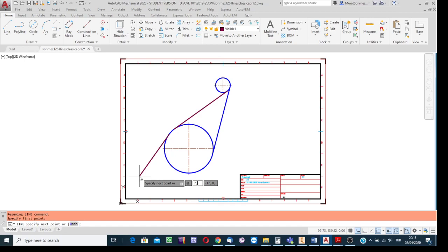But you see in the box there is a negative number and there is no degree symbol. So it is the indicator, and also there is no arc simulation on the screen. It is to distinguish that AutoCAD is not yet ready to take the number which you are going to write into the last box as the inclination angle. What can we do? How can we teach the software that the first number is the length and the second number is the inclination angle?